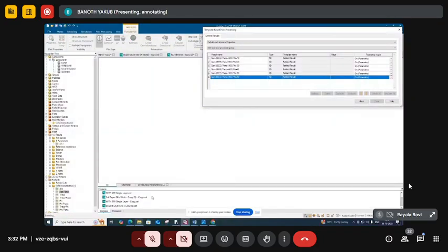After this axial ratio, I will show how much gain we have achieved for this particular antenna. If the axial ratio bands are not matched, we can go to post processing and change the phase angles up to 150 degrees, and theta also you can change to different variations.